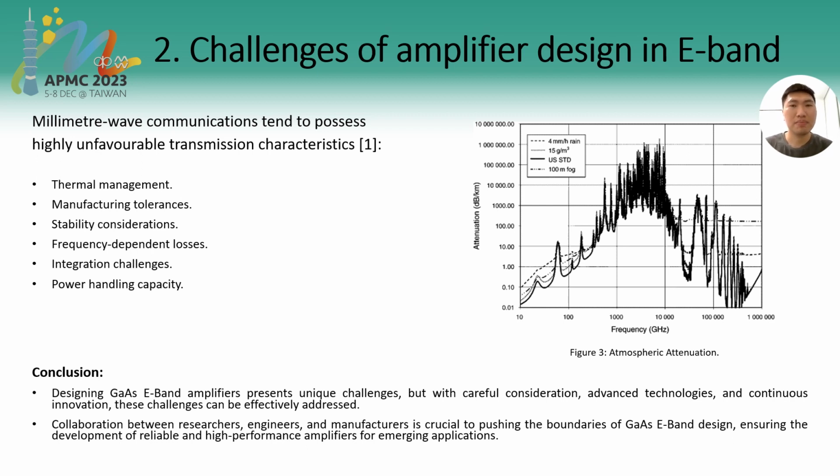Then the frequency dependent losses. The challenge is that E-band signals are prone to higher frequency dependent losses in transmission lines and components. The solution is to optimize the design for minimal insertion losses, and use high quality connectors and transmission line design for E-band frequency.